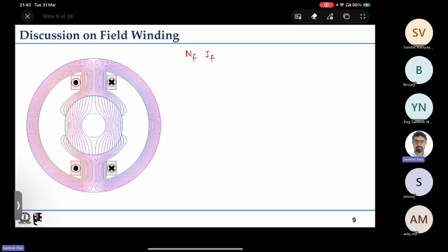So that is why generally field current control is only done to demagnetize, if you want to go beyond the base speed. That is flux weakening. In flux weakening, we generally tend to go towards lower currents.